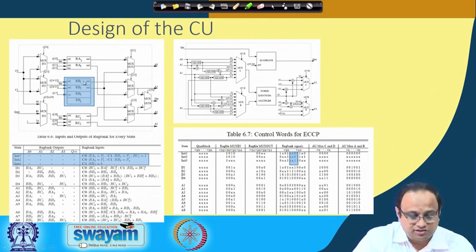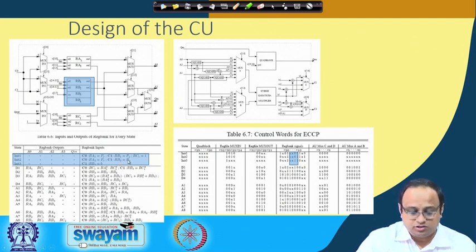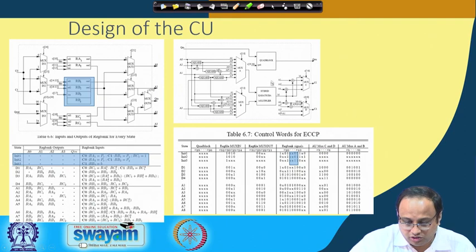So you will see that the second register file is storing, essentially processing, the y coordinates. Okay, so if you observe the steps here, you get RB1 equal to PY. In the second clock cycle you do RB2 equal to PY. So that means you are writing into RB1, and here you are writing into RB2.